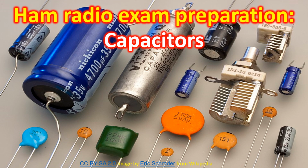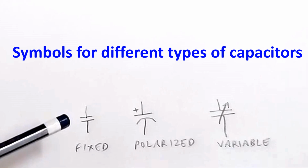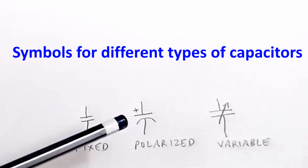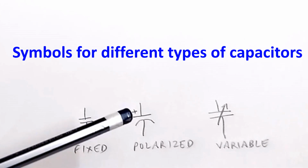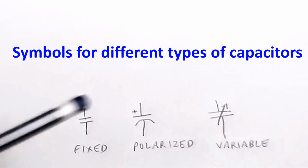A capacitor is said to have a capacitance of 1 farad if it can store 1 coulomb charge at a potential difference of 1 volt. There are few symbols associated with capacitors. This symbol, 2 lines, is for a fixed value capacitor, like the ones which I have shown. And this is a polarized capacitor. Electrolytic capacitors have positive and negative poles which are to be connected according to that in the circuit, while ceramic and paper capacitors or air capacitors do not need that.